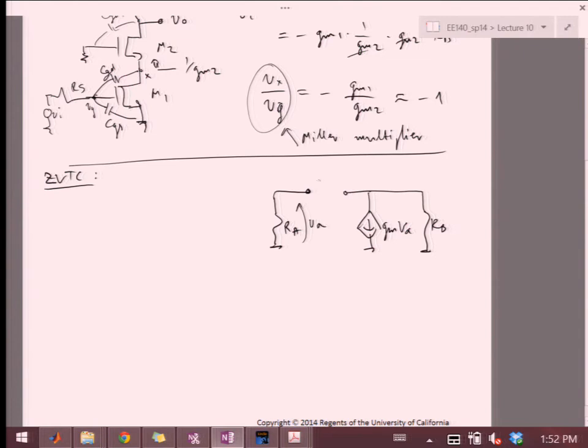And so I'm going to apply VT between these 2 points, and there will be IT as a test current here. This is a typical configuration for when CGD wants to see what the resistance is around. You're going to usually see these topologies, because this RA will be some RS on this side. This RB will be whatever resistance you see up the chain, or the input resistance from the next stage in parallel with your own output resistance, right? And then this is usually going to be your transistor current. And so this is a nasty circuit to just write out the Rin for. But if you remember what the Rin is for this type of topology, it will be very easy for you to crank out the analysis.